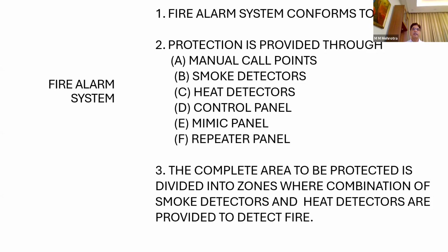So that person who is responsible for security of the building will immediately come to know that there is a fire somewhere. Nowadays, these control panel and mimic panel are integrated. Mimic panel is integrated into a digital display where straight away you can see where the fire is. So I'll skip this mimic panel, repeater panel. These things are nowadays digital, like TV, like screen. It is there in the security room.